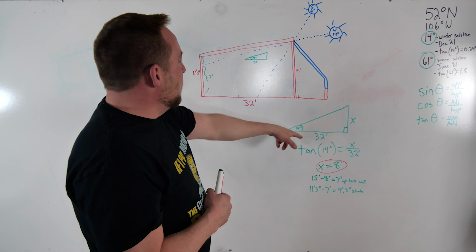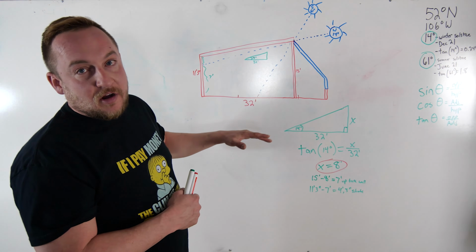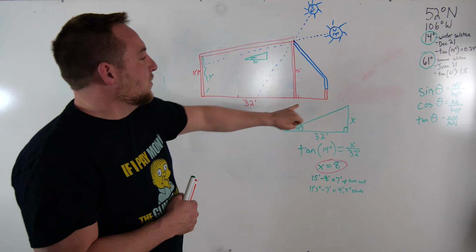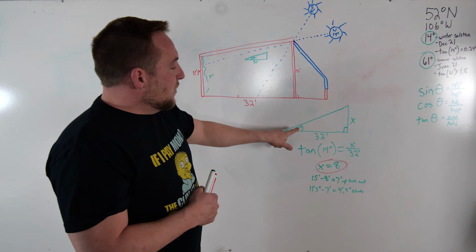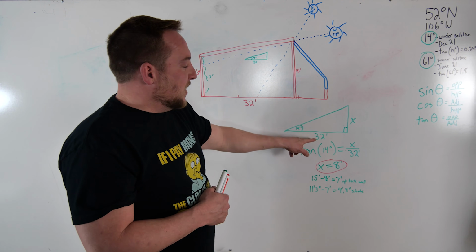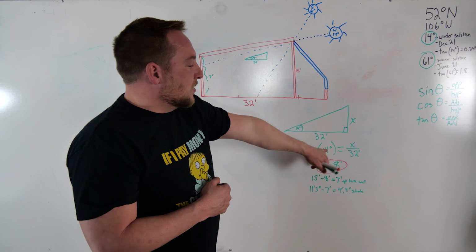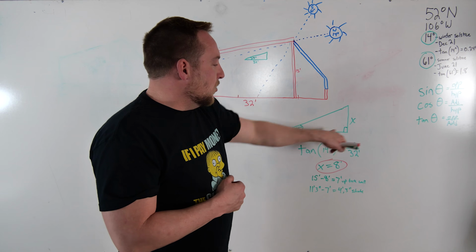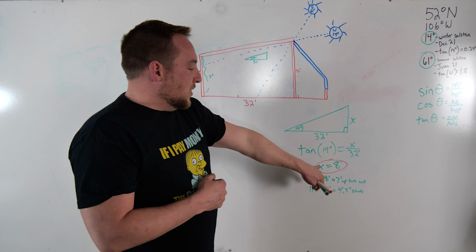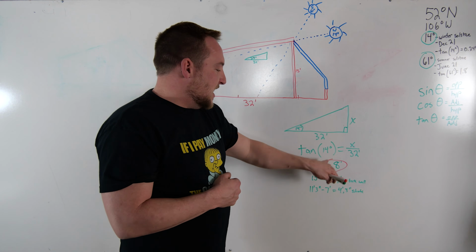So we know that angle, we have to make ourselves a triangle, and let's just do a guess and check. This is what my greenhouse is. It's 32 feet from the post to the back wall, okay? So we know the angles on a right triangle, and we need one side, so let's do 32 feet. So tan 14 degrees is equal to opposite over adjacent, so x over 32. Do that and you end up with x equal to 8. So this side of the triangle is 8.